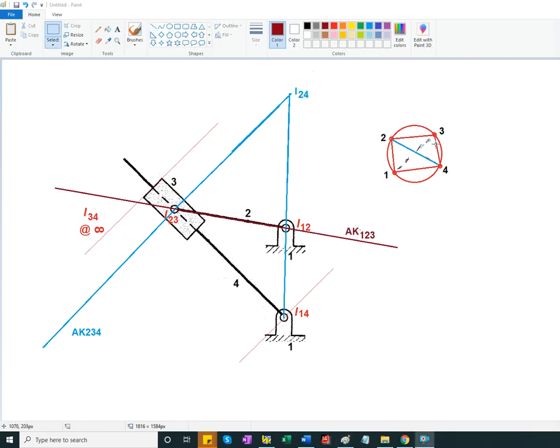All right. So I got myself confused by looking at the blue line. Actually, we're missing the one corresponding to the dash line I13. We drew Kennedy line 1 2 3, and then we need to draw Kennedy line 1 3 4. So 1 3 4 would be the 3 4 line.